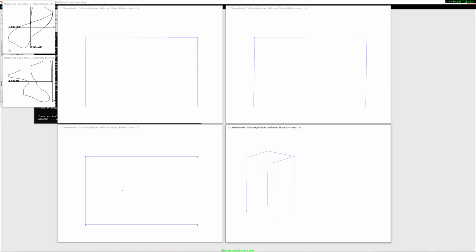What you see on the left is the force deformation response in the x-axis and in the z-axis. Even though we are forcing the displacements, it is displacement controlled in the x direction. It's really cool how you can watch it degrade. In the z direction, you actually do get some forces and displacements, of course, especially because we have some eccentricities in the system.